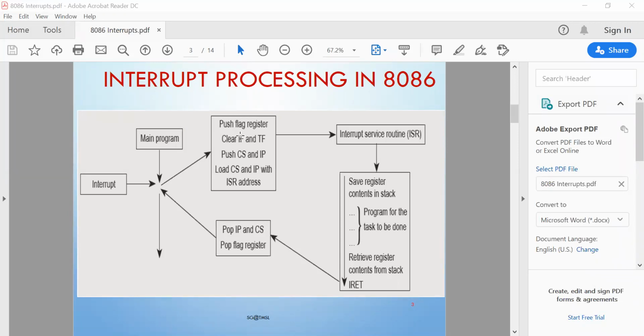Okay, so you have to initialize the stack, because when we are about to execute the current interrupt signal, you have to load the previous instruction execution status onto the stack, so that when it returns to this main program, it holds that previous data, and the next or further pending instructions will be executed in the normal way.